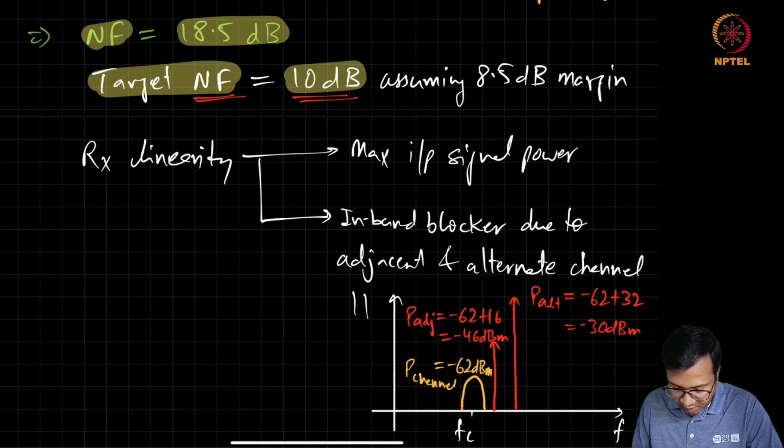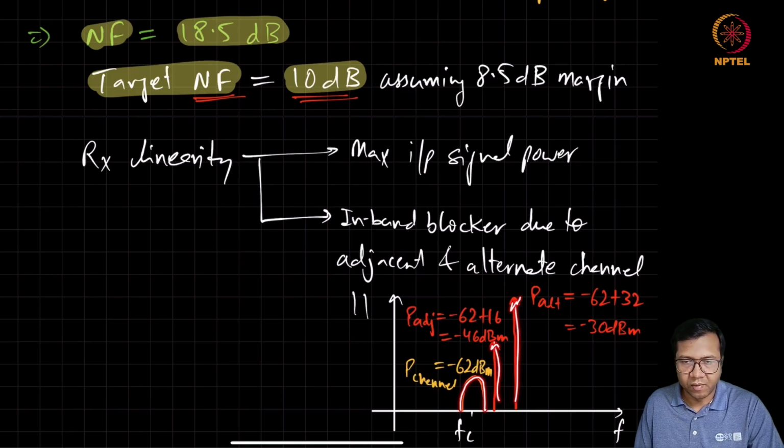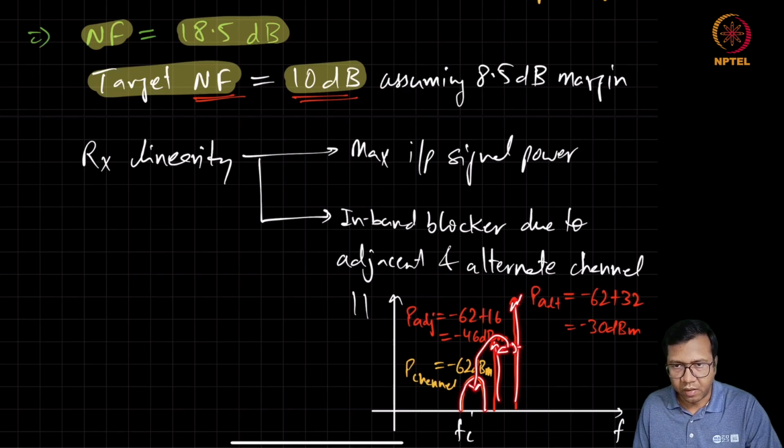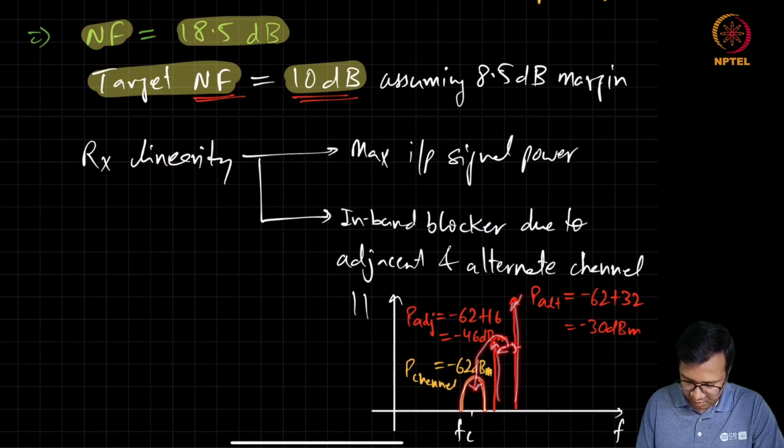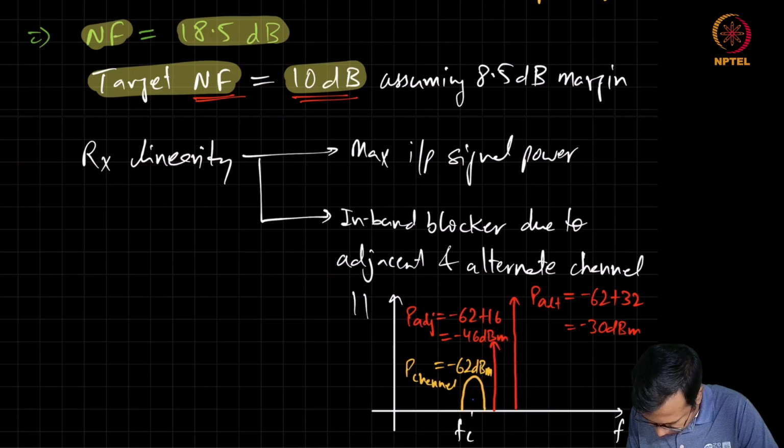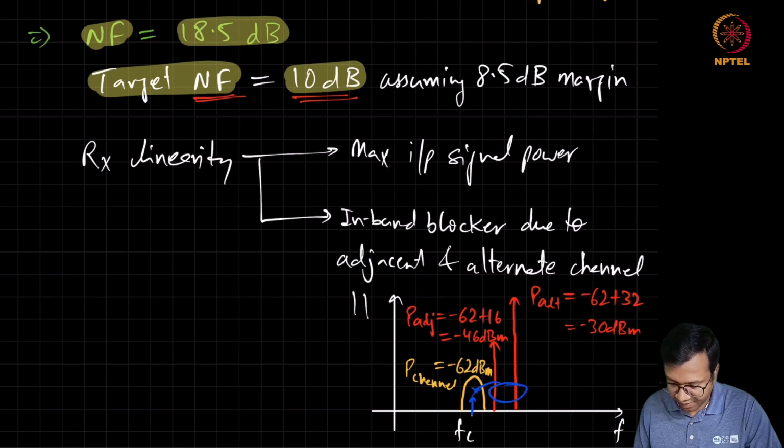So when we are trying to receive signal in our desired channel, these two signals can also be present at a much higher strength, and their intermodulation can give rise to the intermod component in the desired channel. So we can get an IM3 because of these two signals.